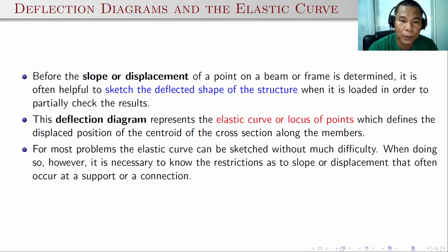Before the slope or displacement of a point on a beam or frame is determined, it is often helpful to sketch the deflected shape of the structure when it is loaded in order to partially check the result. So it's very important that you develop the skill in sketching the deflected shape of the structure. Anyway, don't worry, we will discuss that here.